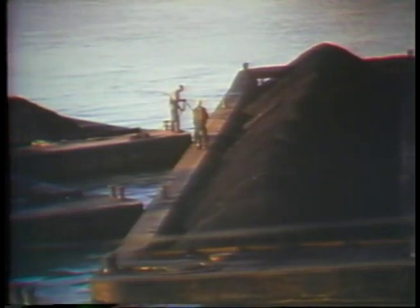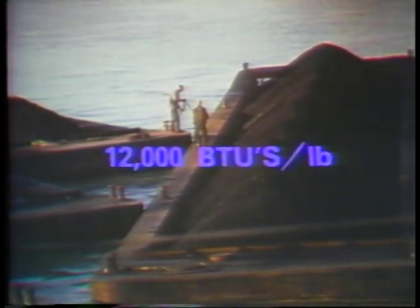This will give you the foundation to understand what goes on in a heat balance. Now, before we actually calculate efficiency in a typical unit, we must convert the energy in coal and electricity into compatible units. We'll make these units foot-pounds. The average coal used in a power plant has approximately 12,000 British thermal units, BTUs, of energy per pound.